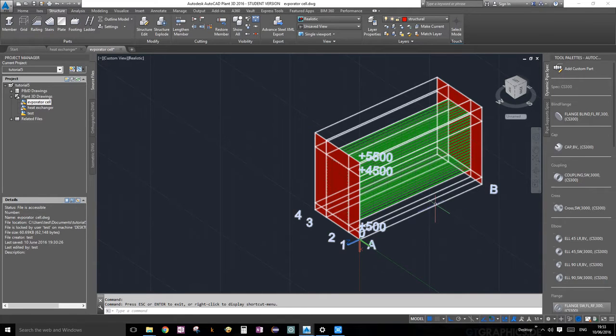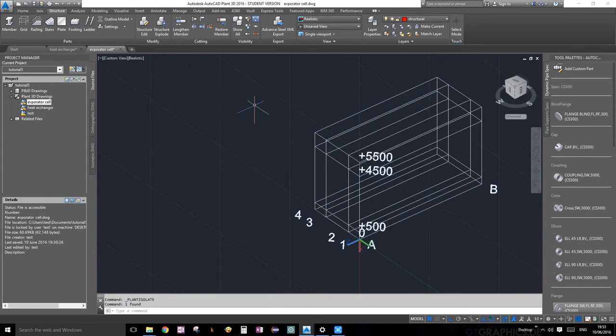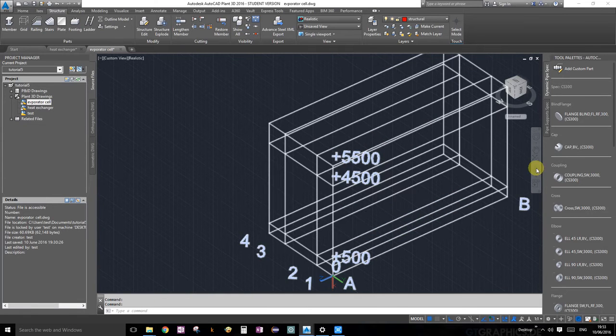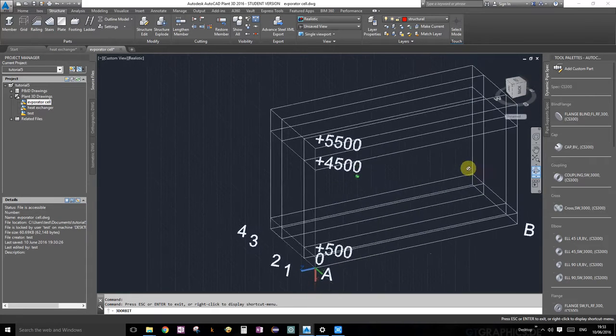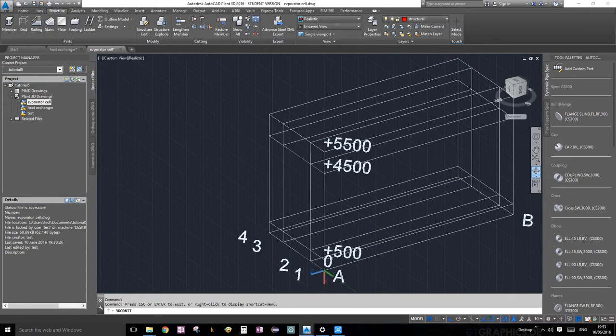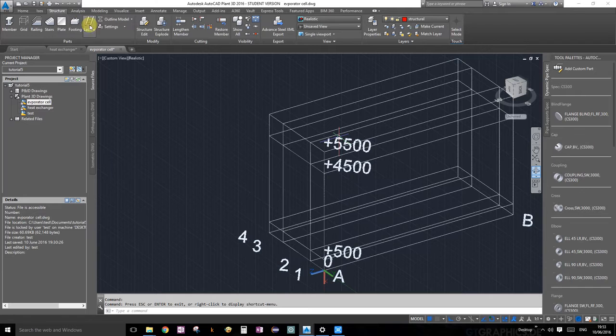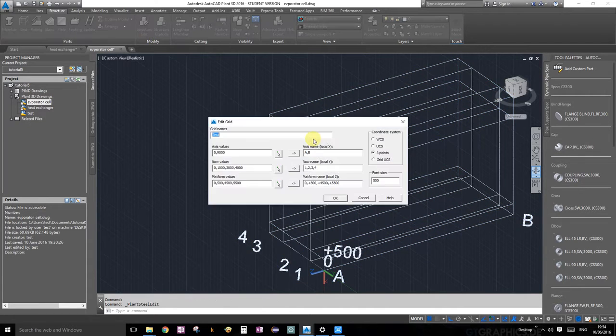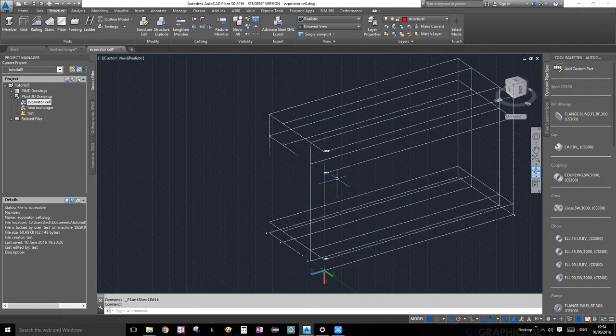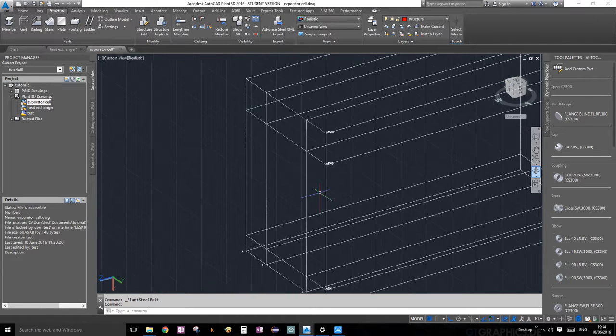So let's select only our grid and hide everything else. Okay, perfect. Now I will show you guys where we're going to create our cover. I know it's a bit hard to see, but I'm going to reduce the size of our font because it's always getting in the way. So let's click our structure and go to structure, edit, and font size. I'm going to make it 50. Perfect. I think it might be a little too tiny, but I think that will do.